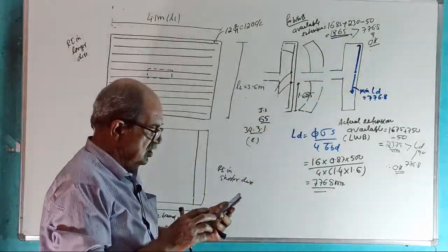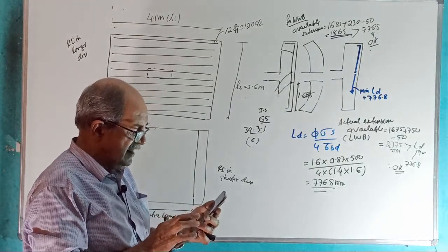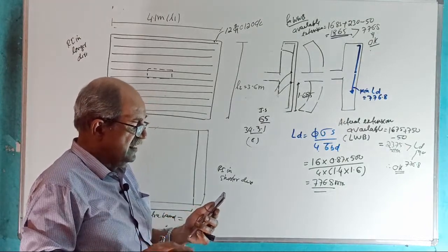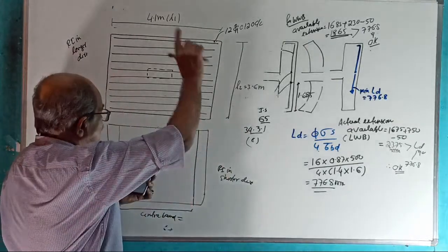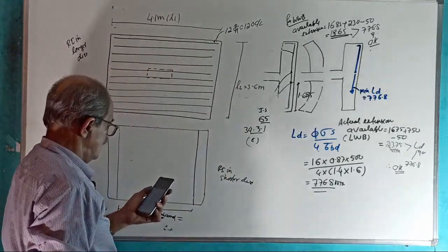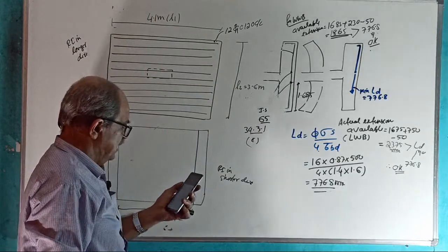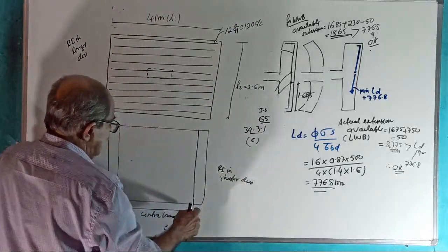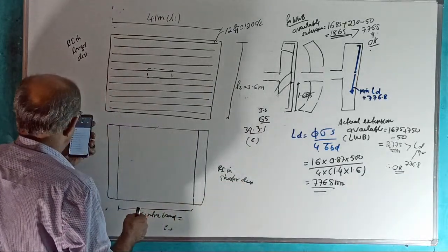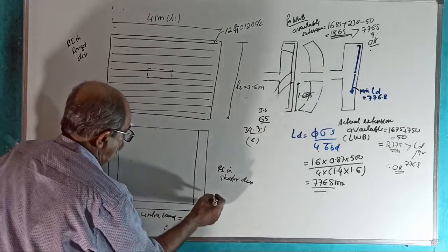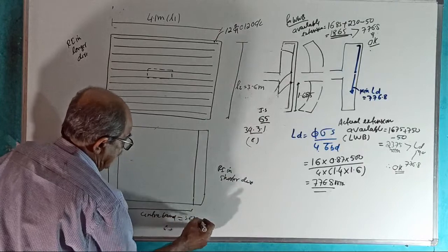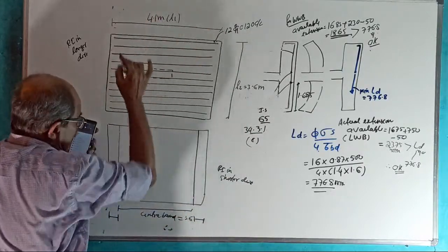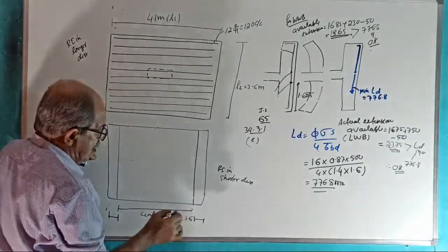Okay, now I have to once again go to chart section. Tell the answer. Width of footing. For this bending, what is the width of footing? 3.6 meter. So, therefore, tell the offset here. From 4.1, subtract 3.6, divide by 2.